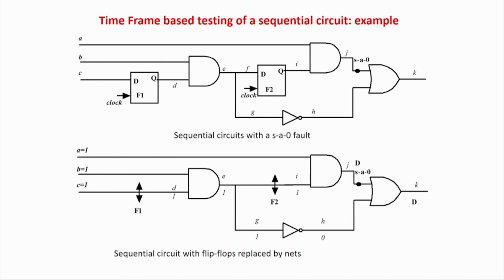Now, if you say, what if I use a scan chain? Scan chain will solve your problem, but still the time taken will be very, very high. Scan chain actually solves the problem in a very indirect manner. As I told you, there are two ways of optimization, if you have seen my lectures on ATPG in this module: how difficult it is to generate the test patterns and how difficult it is to apply them.